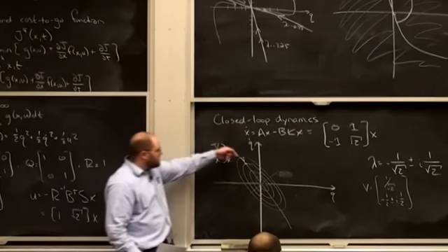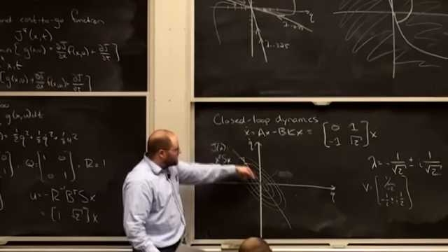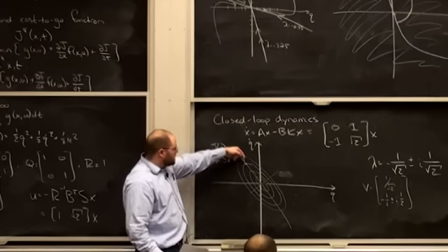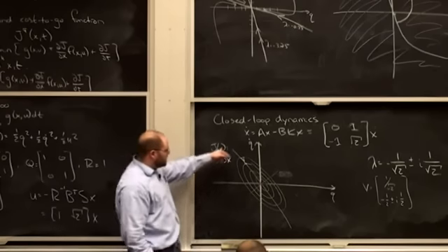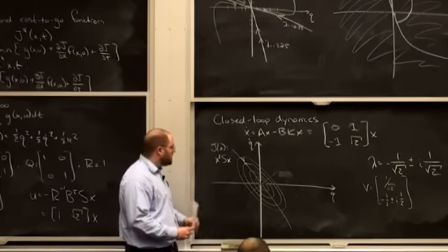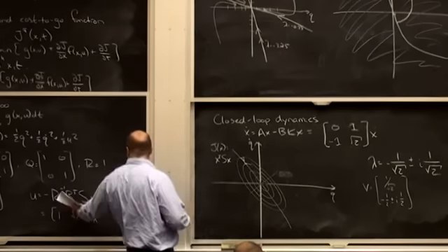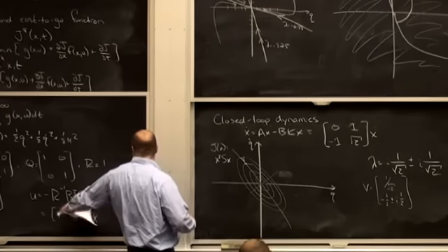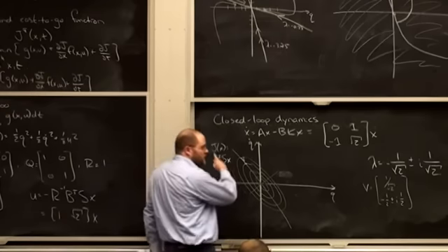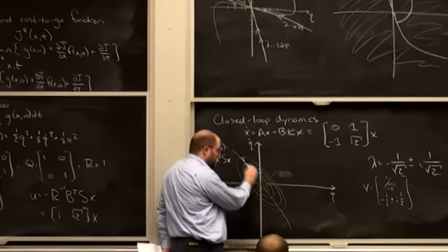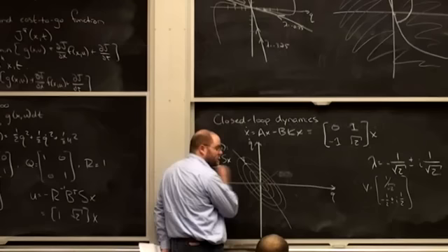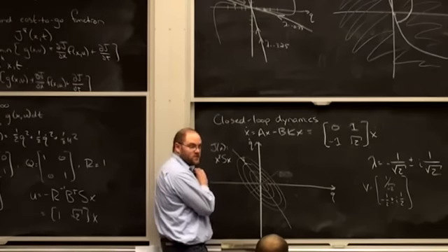The best thing I could possibly do is to go down that. If I didn't worry about penalizing R, my control actuation, it would be to go straight down that bowl. But because I'm filtering things by what I can actually control, and I'm penalizing things by R, the actual response is a complex response, which goes down this bowl and oscillates its way into the origin.